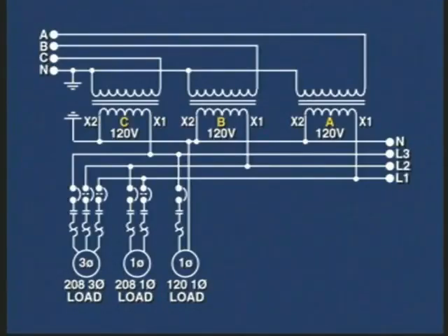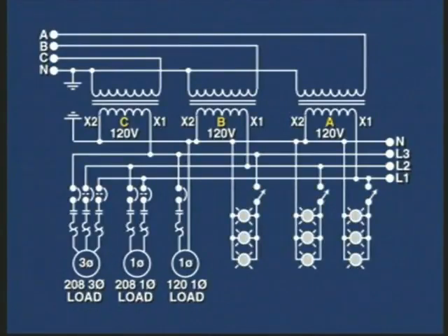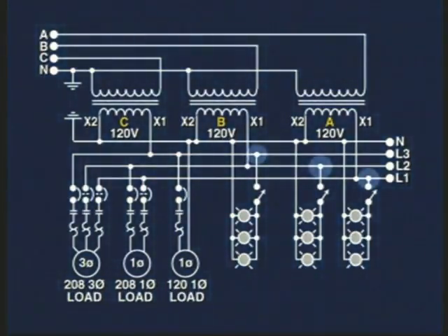We could also have a connection like this in a branch circuit, which is perhaps applying a 120 volts lighting system. Note that in this small example, we have connected each of the 120 volt lights to different phases to try to maintain a balanced load for all phases.